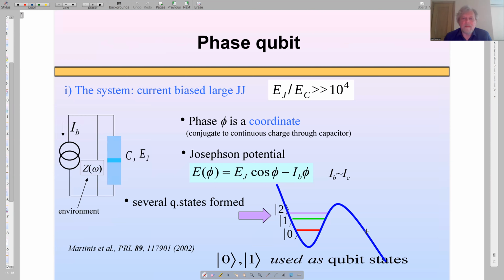Alternative design. Also very simple, a very different region of parameters, very big value of Josephson energy, single junction. In that case, to understand how it works, let me recall the washboard potential we've been talking about. Washboard potential for a Josephson junction.